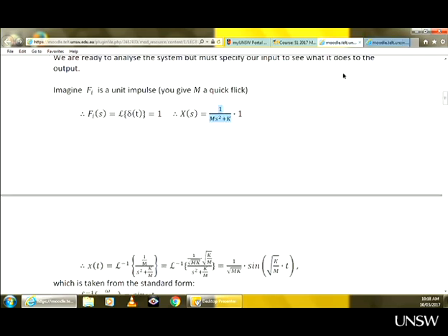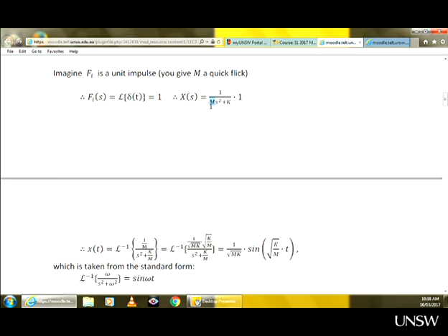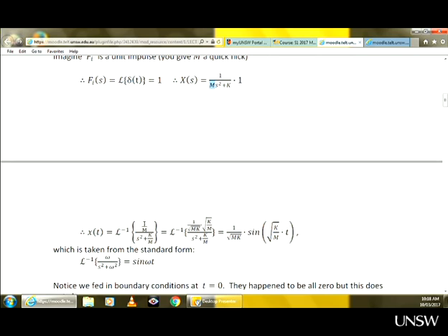First thing, I forgot that. First thing, this coefficient has to be 1. That's the first thing you have to do. Then compare the coefficients. In our case, this is not 1, this is m. So we divide by m both the numerator and the denominator here. So as a result, we get s squared. The coefficient with s squared is 1. That is what we have here.